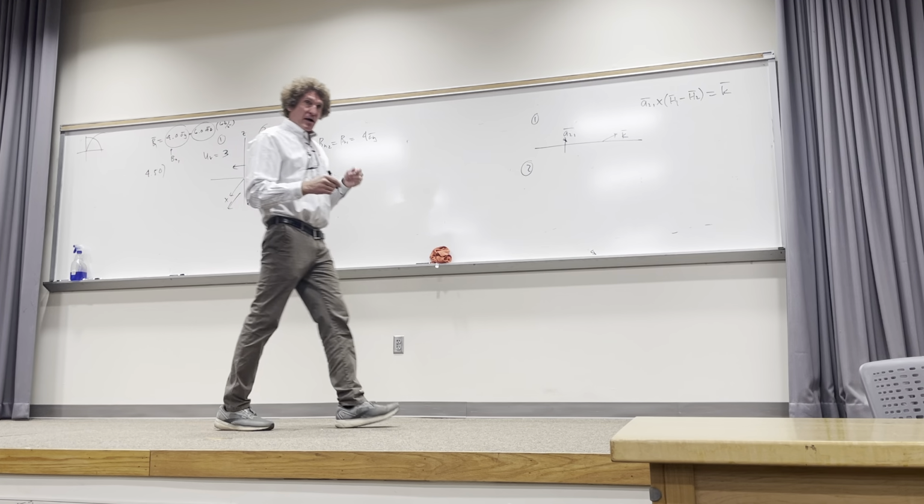I know B is equal to mu H in region 1, so to get H in region 1 I take B1 divided by mu. So I have 4AY plus 6AZ over mu naught, and then mu relative in region 1 is 3, and that's H in region 1.